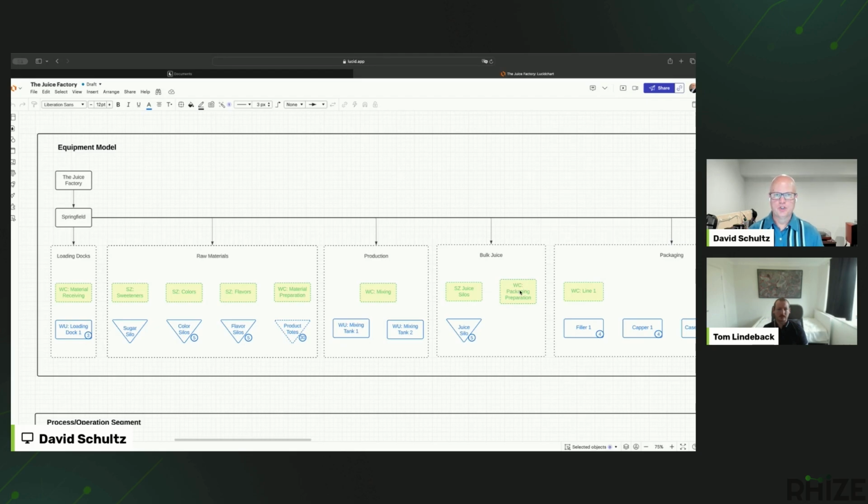Awesome. Yeah. The scope of this is just the effort going on here, this internal process. That would come on an iteration, but not a problem, because now all we do is add in that work center, add in the equipment associated with it, and all the resource models, and we'd be able to take what we already did and continue to build out the model to account for that use case. Yeah, definitely one of the advantages of ISA-95 in that way. You can start small and keep adding on, and it doesn't ruin what you've already made.